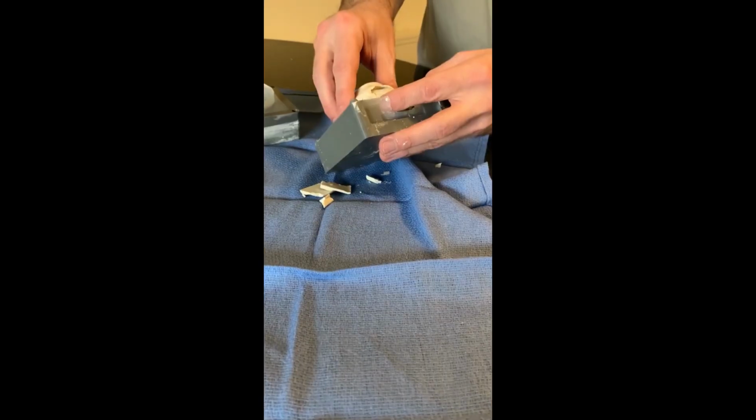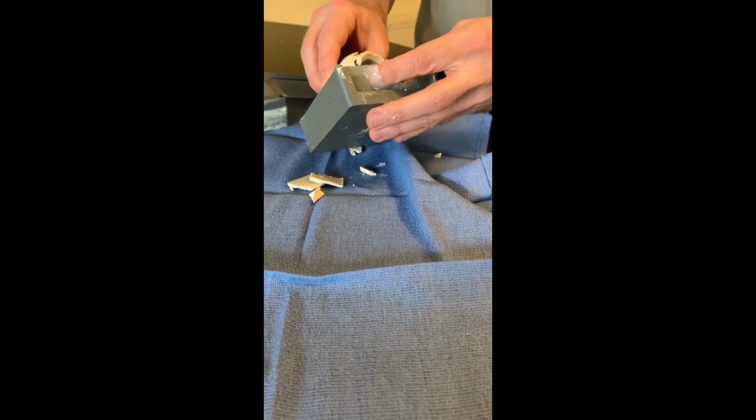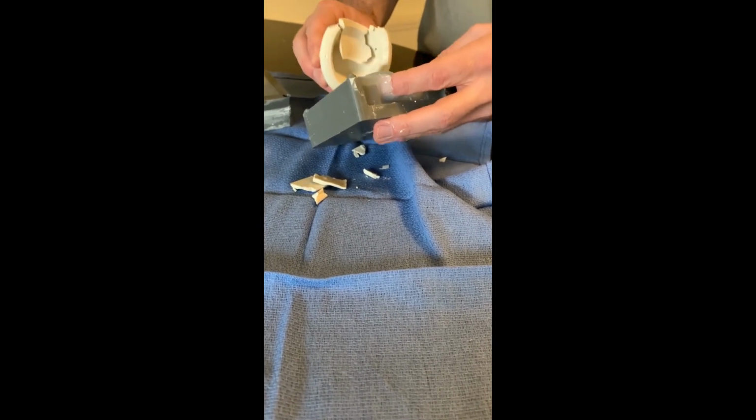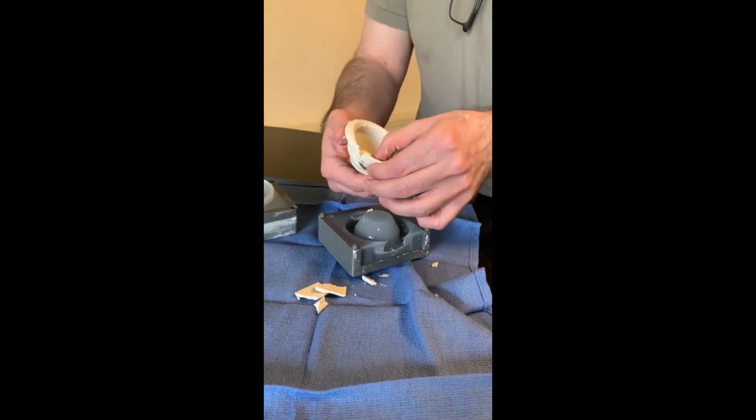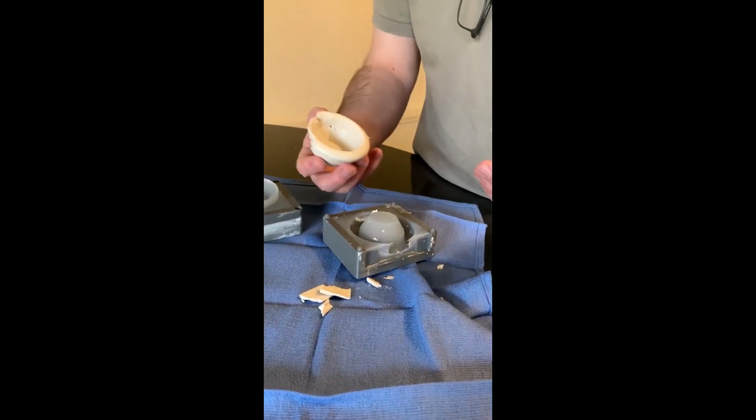So you have to decide if you need a sprue and a riser, and if so, whether you want to place it yourself or let us place it. Now for best results on a lot of pours, you want to integrate a funnel and a sprue into your design. You pour the resin into the funnel and it fills the mold in a very nice controlled way.